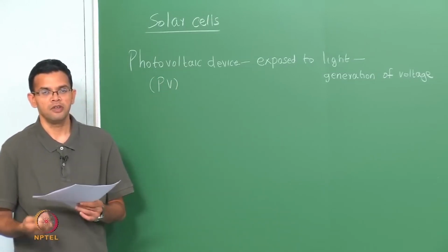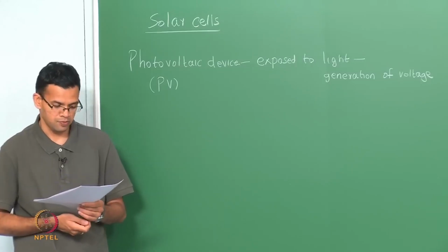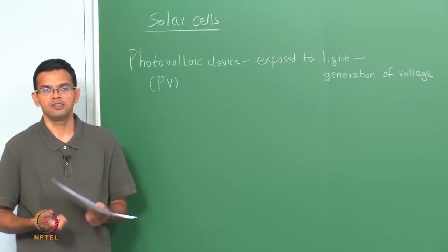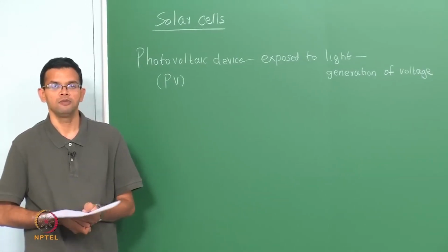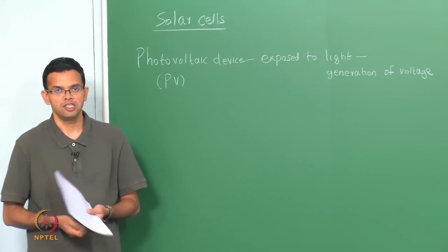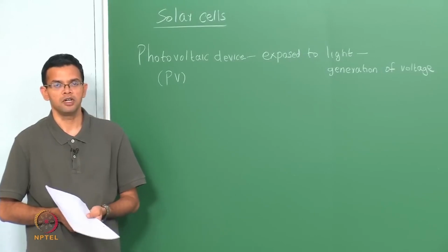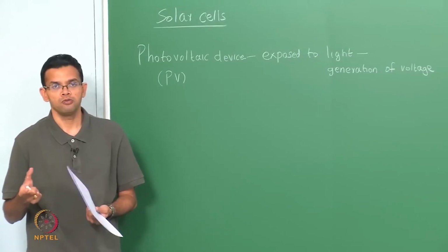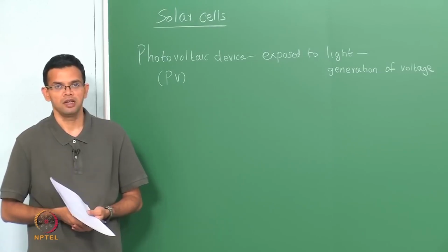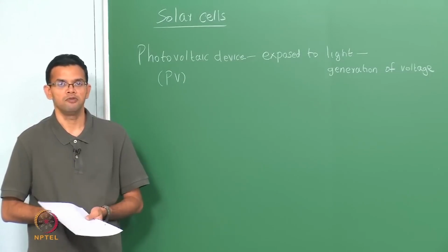photodetector that we looked at last class. There are just a few crucial differences. In the case of a photodetector, we saw that one such example was a photodiode. It could be a simple p-n junction or a pin junction. A photodetector works over a narrow wavelength range. The maximum wavelength depended upon the energy of the transition that was involved.